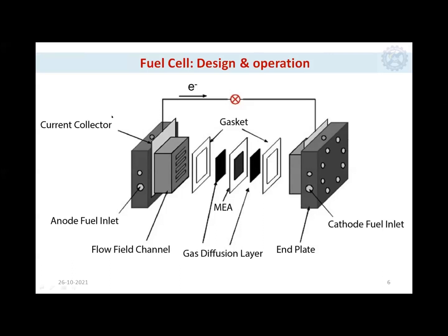And the second set of components are gas diffusion layers. These are all kind of packings to your electrode that protect your catalyst. And these GDLs should have very good gas permeability. Otherwise, there will be some resistance created because of the depletion of your reactant. And you have gaskets to compensate the height of these GDL and catalyst layers.